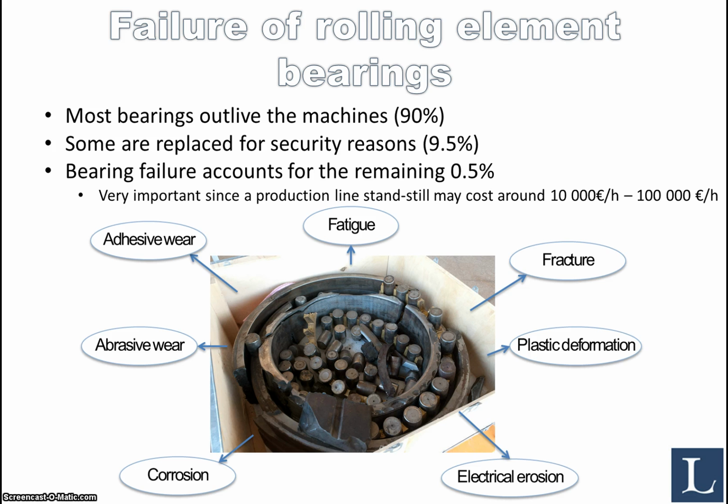Now, the important thing is to remember that most bearings actually will outlive the machines. I've shown some figure here of around 90% of the bearings that actually outlive the machine that the bearing is mounted in. A little bit less than 10% are replaced for security reasons. I mean, you do regular maintenance and you replace bearings that you expect are about to fail. And bearing failure accounts for the remaining 0.5% of the bearings. That may seem very insignificant, but it is a very important